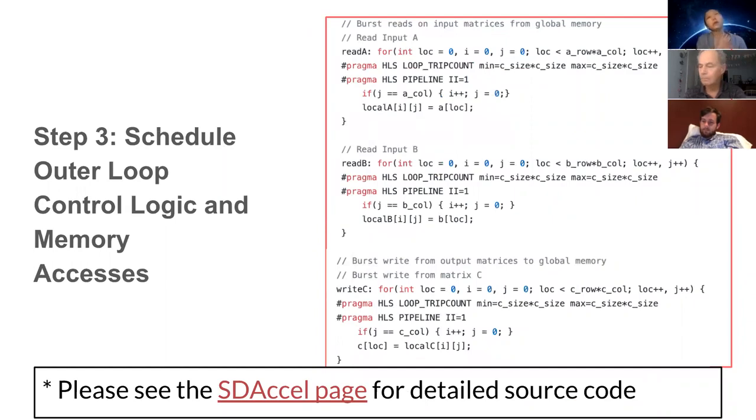The innermost part is not so difficult normally, because it's normally a very structured compute, and it can mostly be synthesized into combinational logic with pipeline. But the harder part is how you specify things in control logic in high-level synthesis. So here, we first read the input image from the global memory. The global memory will be specified as an array.